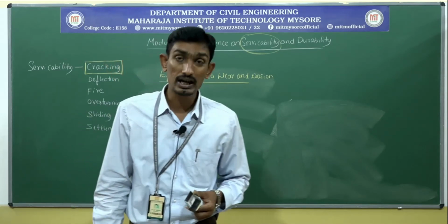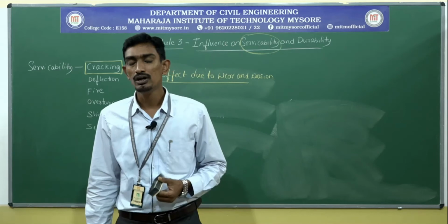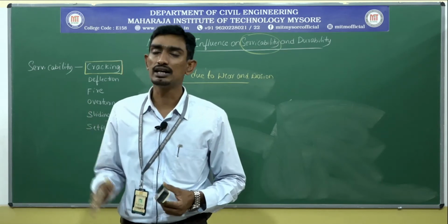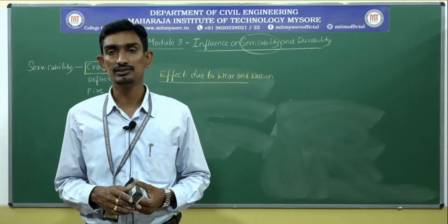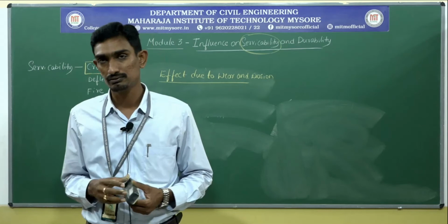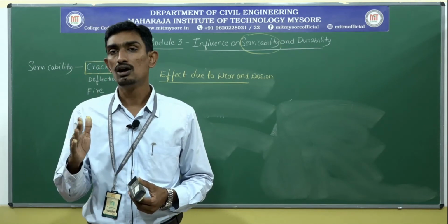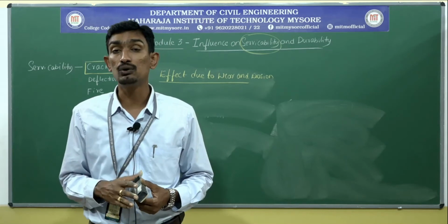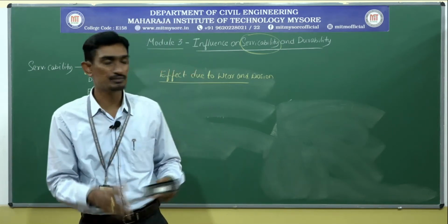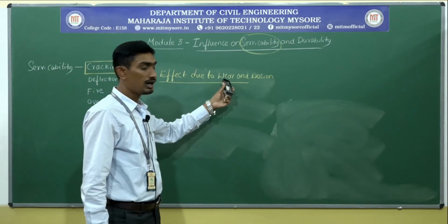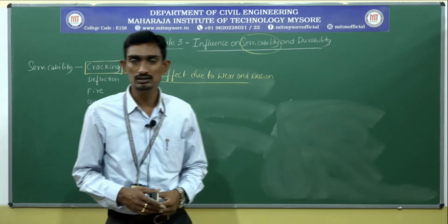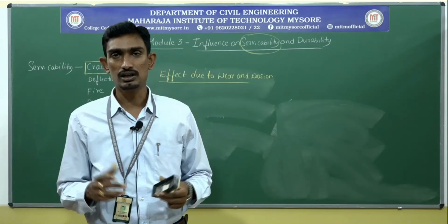Next, what about erosion? It refers to the wearing away or removal of a concrete surface by fluids or liquids. A flow of liquid on the concrete surface is also dangerous and will lead to erosion. Have you understood? Wear means wearing of a surface by friction. Removal or wearing of a surface by liquid or any fluid, mainly water, is called erosion. So this is the terminology.